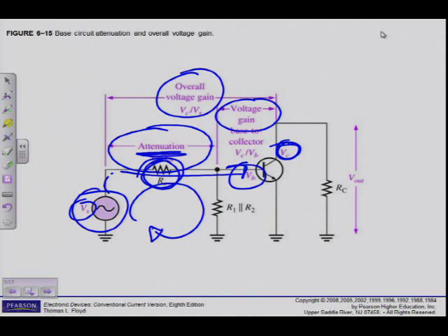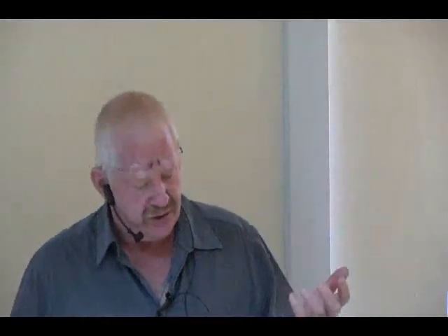It says, for example, if the signal amplitude is reduced by half, the attenuation is 2. Now this is a bit confusing. I don't really agree with the guy that wrote the book, because he's just told us that the gain corresponds to a value of less than 1. But you will see here in the end, what he does, he gets the reciprocal of that number, which will give you a value of less than 1. If you look at that formula which says attenuation is equal to Vs over Vb, which to me is actually the wrong way around, which is Rs plus R in total divided by R in total, of course that is not going to give me a value of less than 1, but you will see then he gets the reciprocal of that.